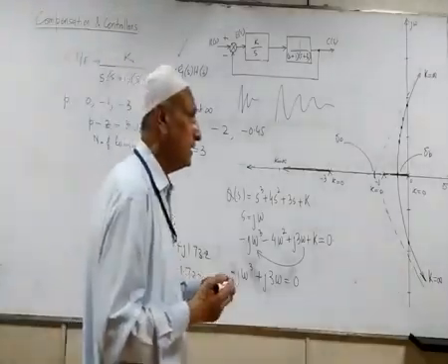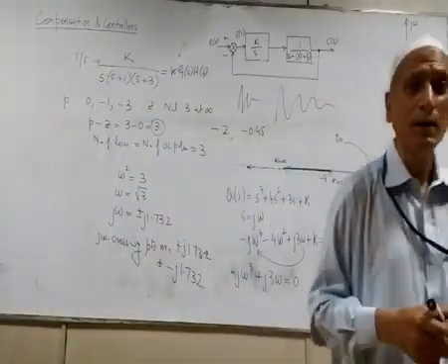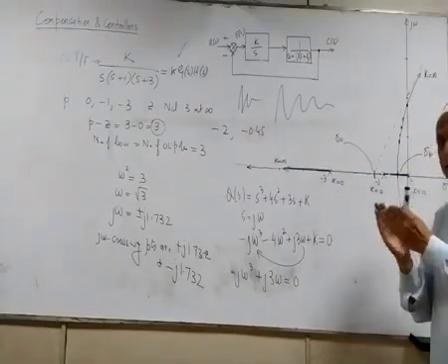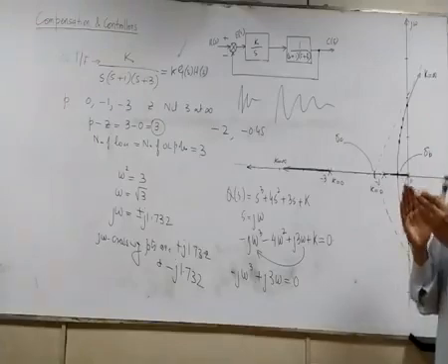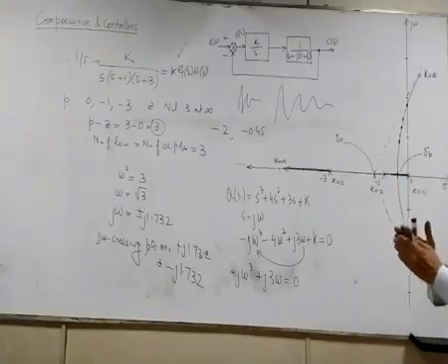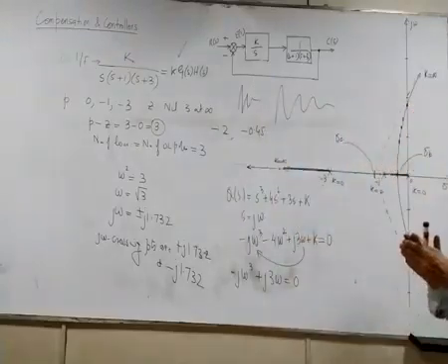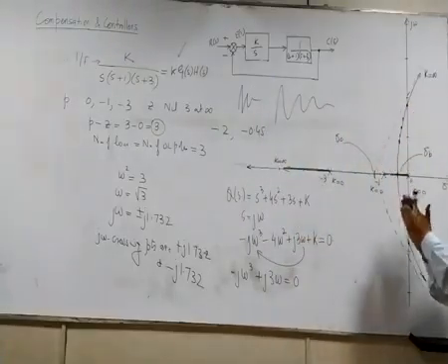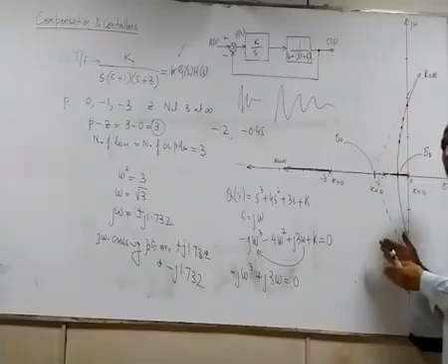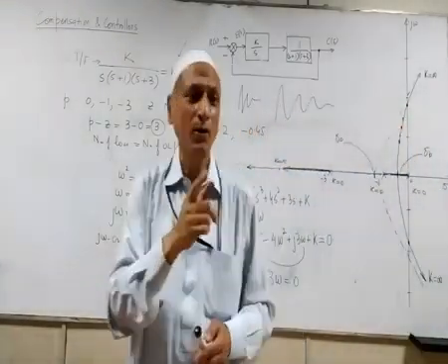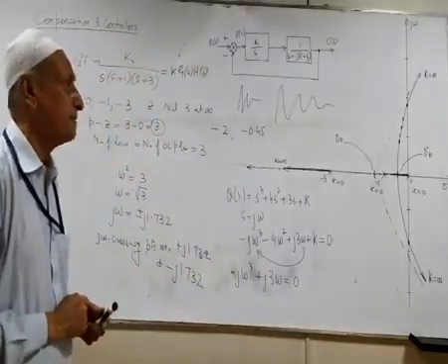So, in fact, a derivative controller actually puts the system right according to the proper transient response, and then the incorporation of an integral controller would make the system gain increase to improve the steady state. However, it will be at the expense of deterioration of the transient response.